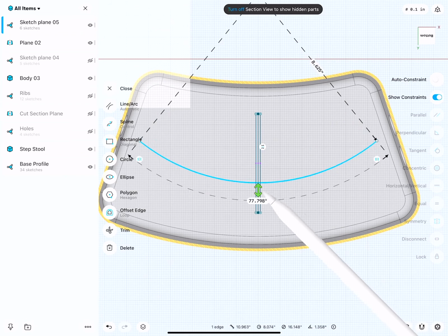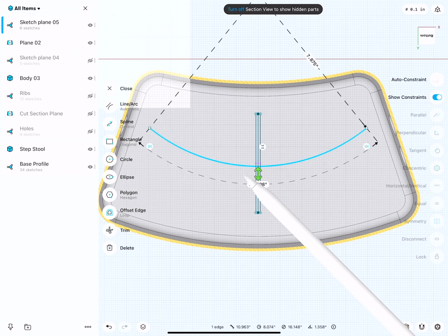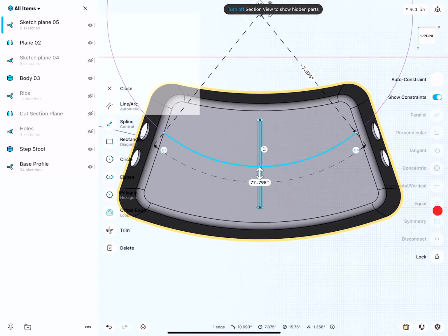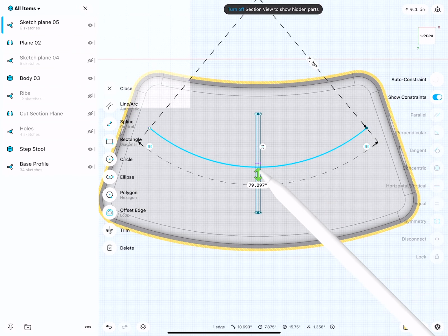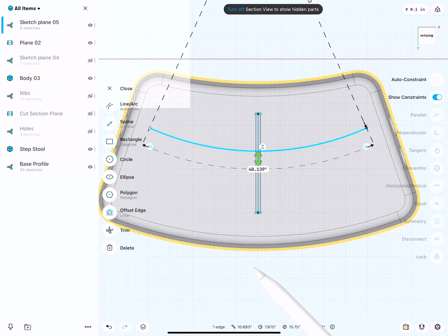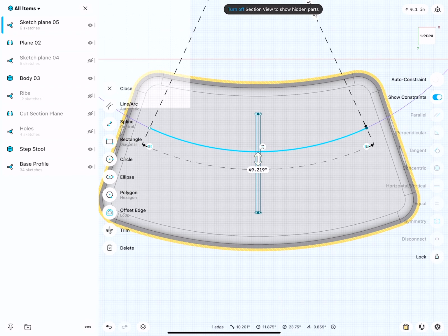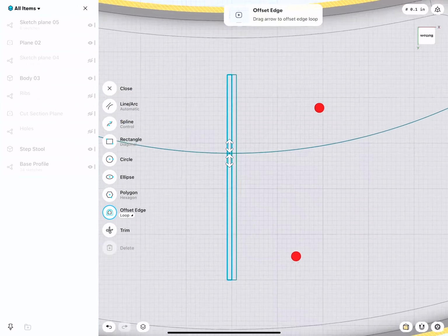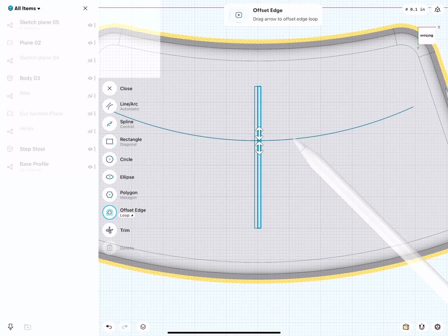You see now if I adjust this, just scaling it, but I want to change the radius. How do we do this? Very easy. We simply lock a point. Now this is much easier to adjust. So I have to find a medium value between the upper radius and the lower radius of my model. We can add then also here an offset.